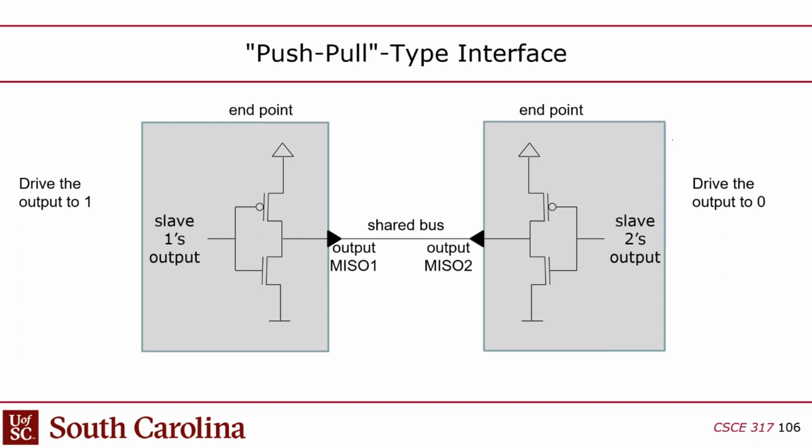The problem is that if one of them is trying to pull up, in other words, trying to put a logic 1 out, he is going to be turning on the PMOS transistor and turning off the NMOS. These are complementary, so either one's always on and the other one's always off. So I'd be pulling up, turning on the top transistor, which is a PMOS, which is going to be shorting the output to VDD, to logic 1, and then the NMOS would be turning off. So basically, you're just creating a low impedance path between VDD and the output wire. That's basically what it's doing.